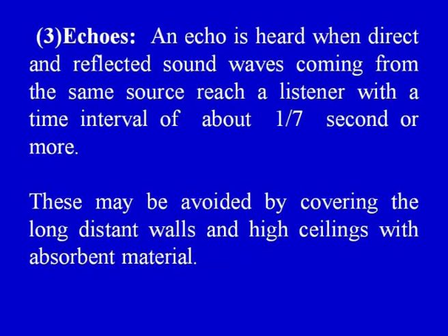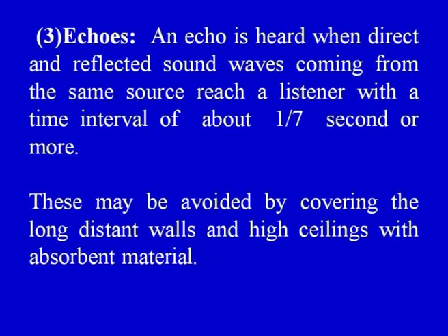Number 3, echoes. An echo is heard when direct and reflected sound waves coming from the same source reach a listener with a time interval of about 1/7 seconds or more. This may be avoided by covering the long distant walls and high ceilings with absorbent material.